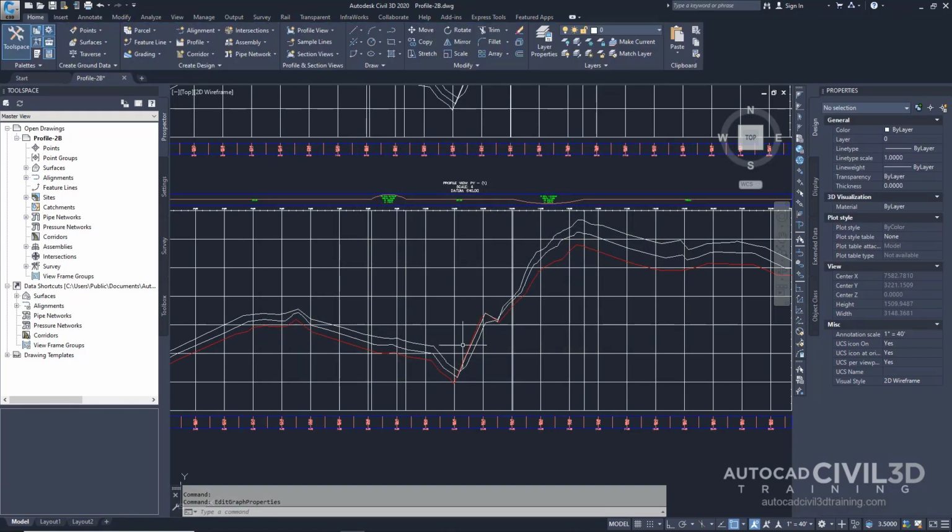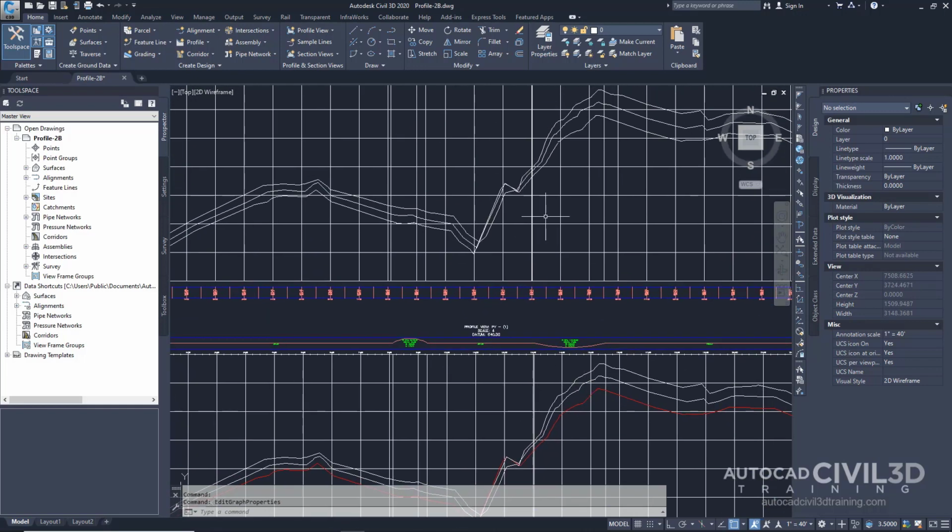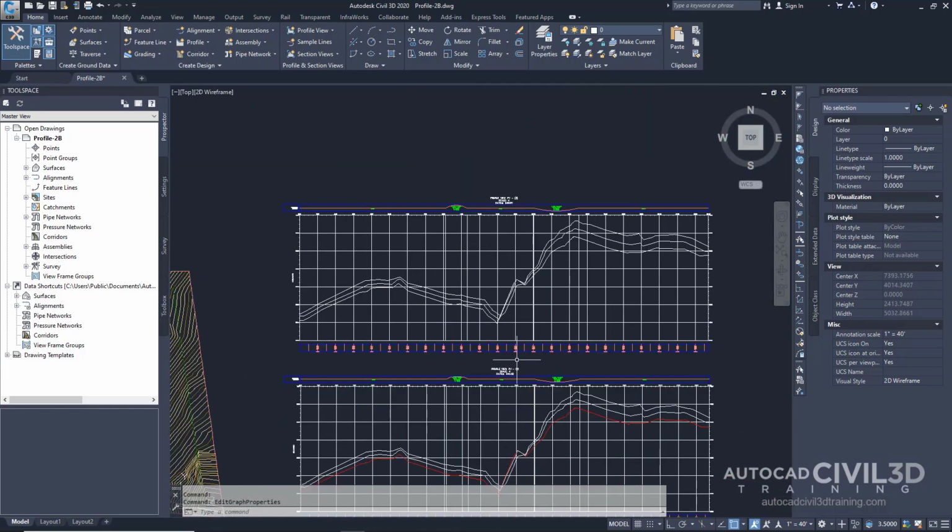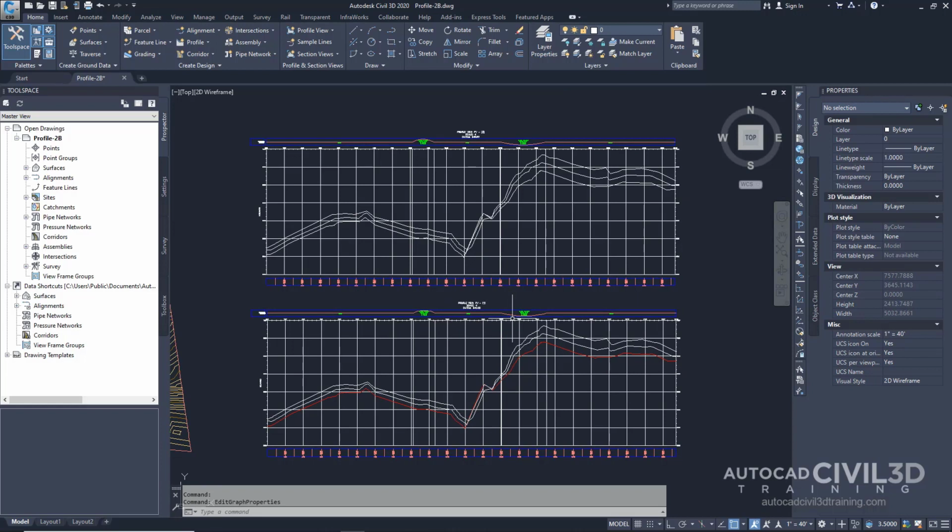The left offset profile changes to red, reflecting the existing ground style in Profile View PV1, but not in PV2. The left offset profiles are different because you can override the profile style for a particular profile view, but you did not change the profile style. You can use the style override to preserve the profile style within a profile view, protecting it from later style